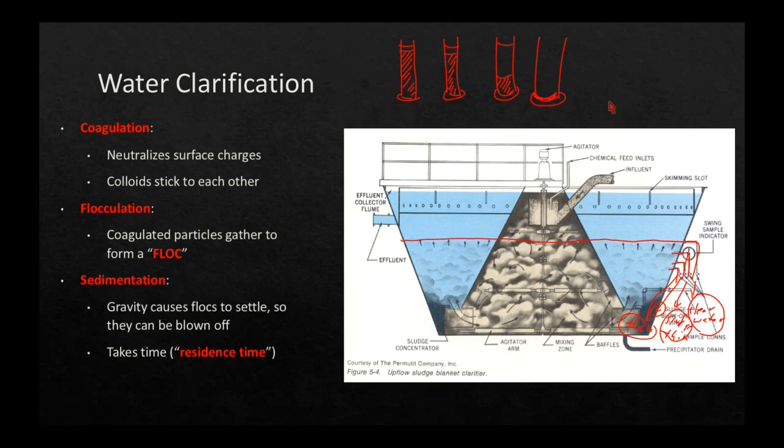where we might have just a little bit of sludge in the bottom. Okay, so this is one of the things that you're going to be doing on shift on a regular basis, maybe every 2 hours, maybe 4 hours. You're going to be doing this because what you're trying to do is figure out the bed density and you're also going to try and figure out the bed height.